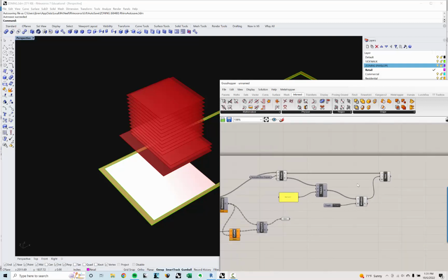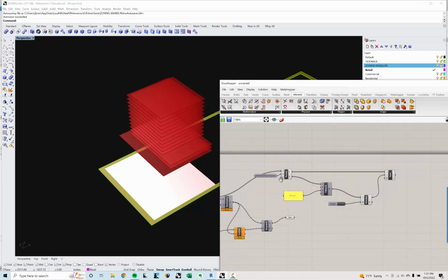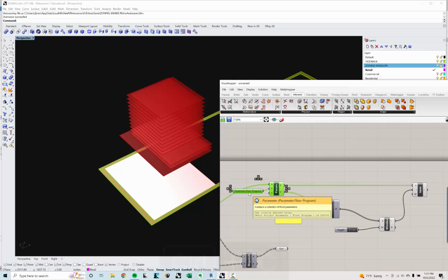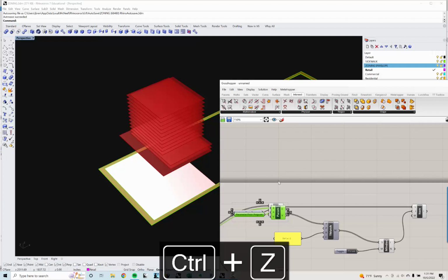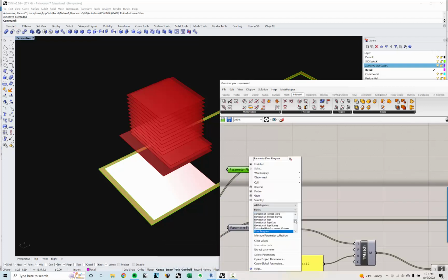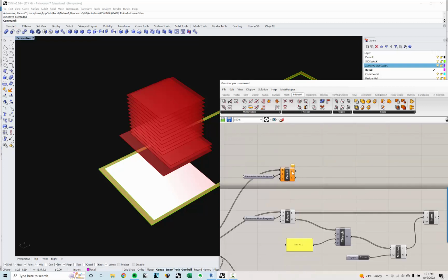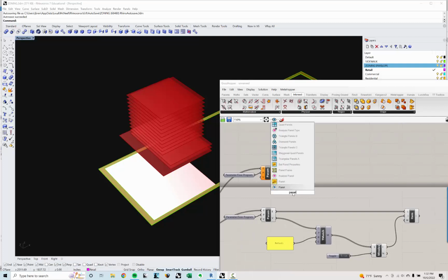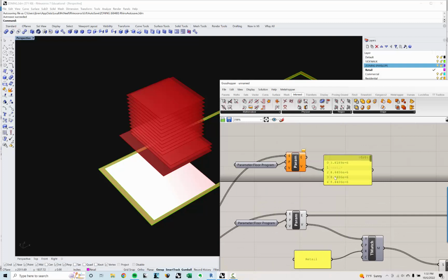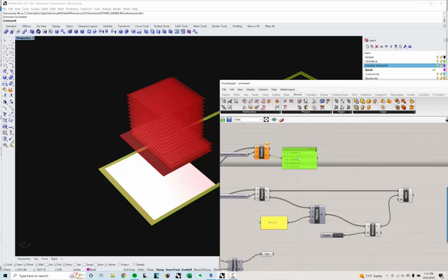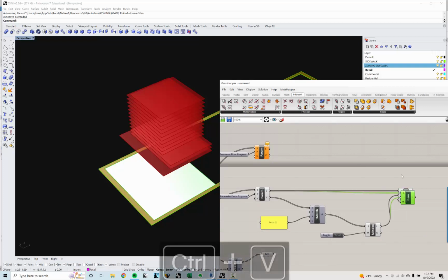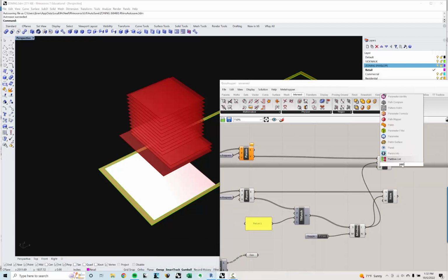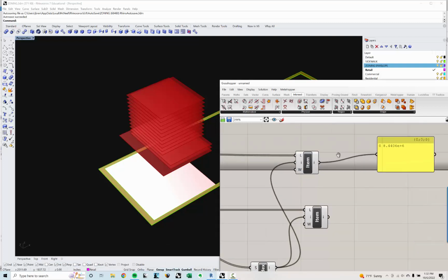So then the next thing we want to do is get how many square feet of retail we actually have. So I'm going to replicate what I've done here a little bit, and I'm going to grab this element parameter. But I'm going to change this parameter here. I don't want floor program, I just want area. Some of them don't have it, which is okay. We have some null values in there, but that's all right. Because the lists are in the same order, all I want is this number 2 value, because that's the same item index as this. So I can just take this same exact component here, copy this. So all I've got now is my area for that.